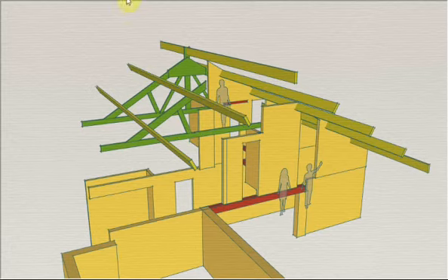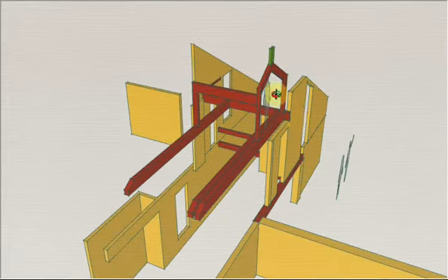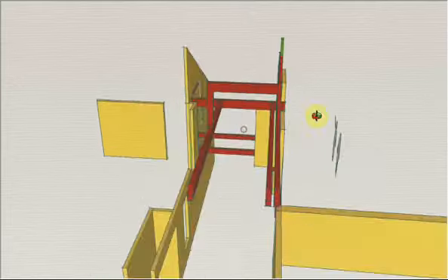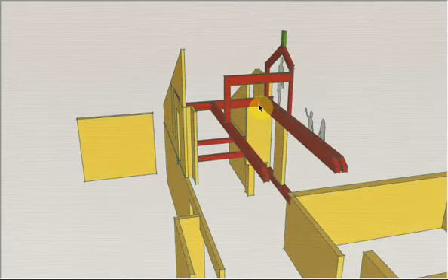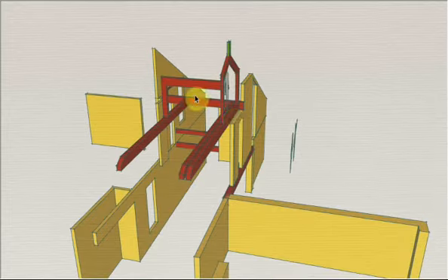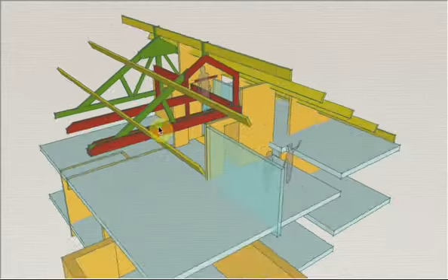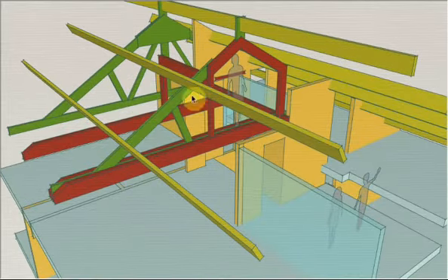So to remedy that, we're proposing some steel work that bears off of the load bearing masonry wall here and here. So there's a beam across here that then supports this beam, and this beam. There is then a post and a further beam that goes across to the framing out point here. Now the framing out point supports this ridge which is to remain, and these two purlins which are to remain are likewise supported. This part of the truss has now been given support from the steel work.